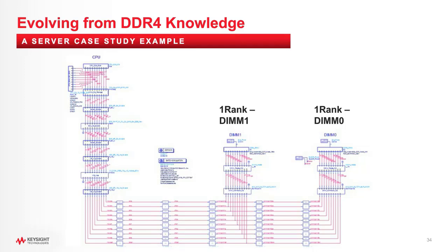So we tend to do things like, well, what would be a minimum impedance corner, a maximum impedance corner, and then a length like a short, medium, or long length for each of these particular traces. And then doing the same for corner cases for the silicon as well. So in particular for things like IBIS models, you've got a fast and slow model corner, and it's very appropriate in pre-layout to try to sweep through all of these.